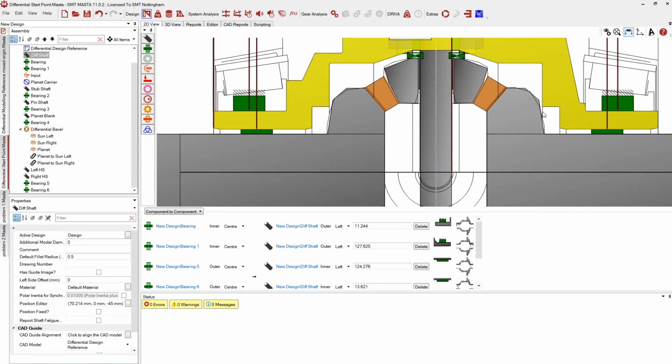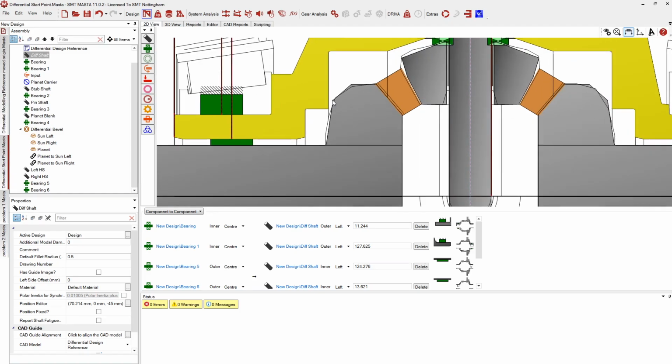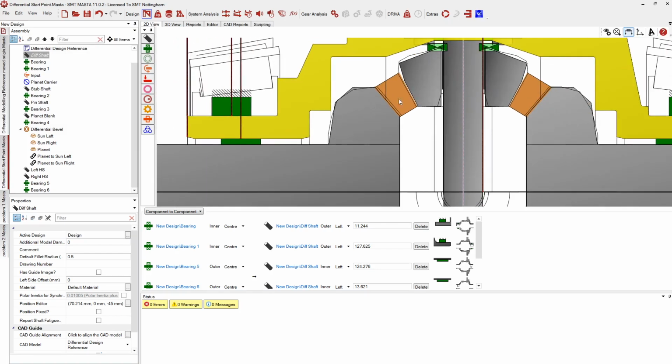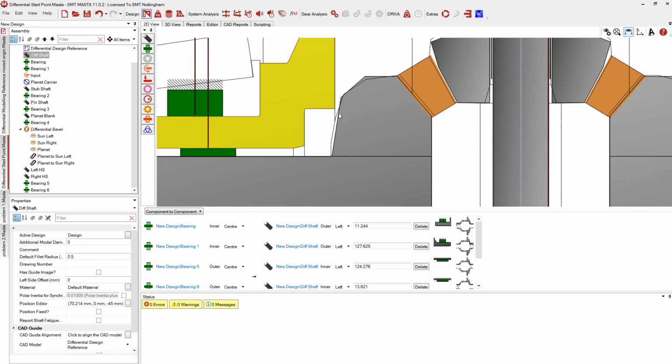And then a couple of axial clearance bearings at these two locations here. And again, that's just controlling or constraining the axial motion of that system, because there will be some load coming through the differential here. It's just if it gets pushed in that direction, we want it to know that the load will be transferred to the differential casing in this case.